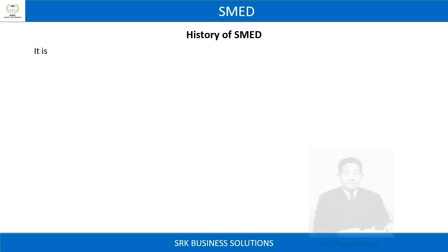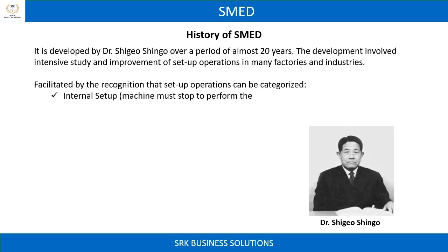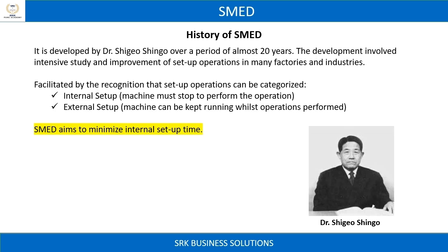Now we will see the history of SMED. It was developed by Dr. Shingo over a period of almost 20 years. The development involved intensive study and improvement of setup operations in many factories and industries, facilitated by the recognition that setup operations can be categorized into internal setup, where the machine must stop to perform the operation, and second, external setup, where the machine can be kept running whilst operations are performed. SMED aims to minimize internal setup time. Dr. Shingo is known as the father of SMED.